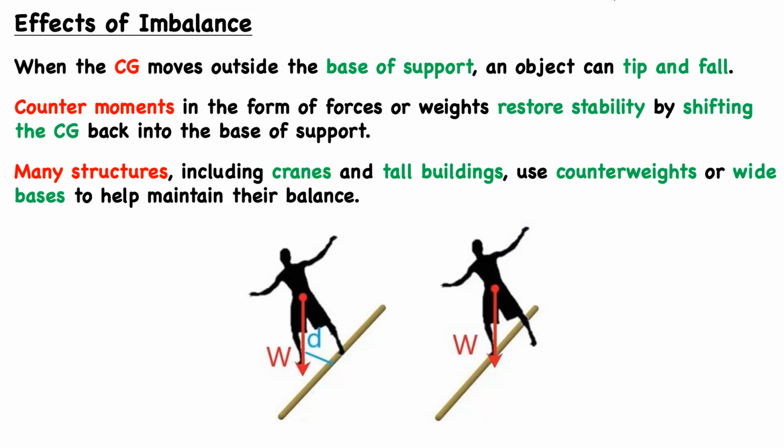So in this case, it's very important that these structures are designed with a correct or appropriate center of gravity to ensure stability. And they do that by using counterweights, which can help lower the center of gravity, or likewise can use wide bases, which essentially play the same role. You're not actually adjusting the center of gravity directly through changing the weight distribution, but you're instead widening the base, you're increasing the area or the base of support, which also helps to improve stability.